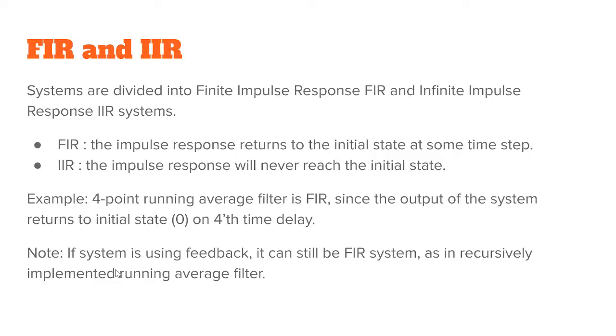Infinite means that it never ends. It's like any analog RC filter. It decays but never goes exactly to zero. It goes very close but never exactly zero. So, for example, that 4-point running average filter is FIR because after the 4th time delay, the signal is zero on the output.